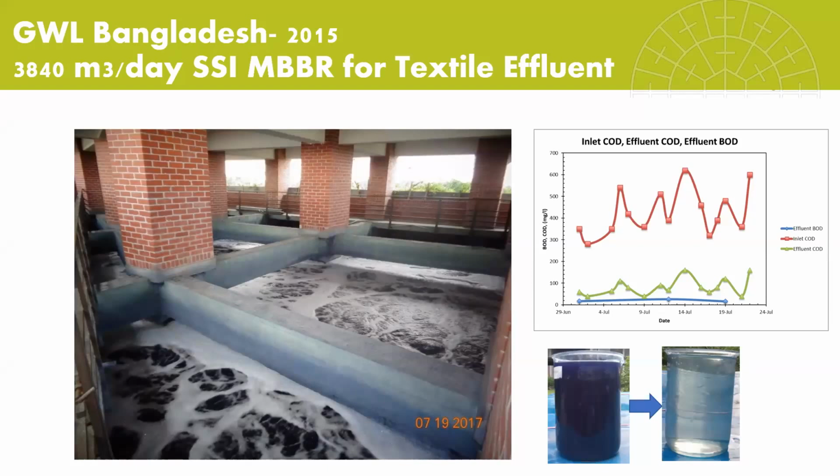Excuse me. So how did we get to that point? Well, part of that was looking at the primary systems. For this particular denim washing facility, we recognized that there's a lot of fiber and stone in the system, so we had to be very careful with the type of primary system that we put in place, as we did not want fibers and stones to make their way to the equalization tank or the biological tank, as that will create issues over time. So Kelsey, if you want to jump ahead to the next slide.